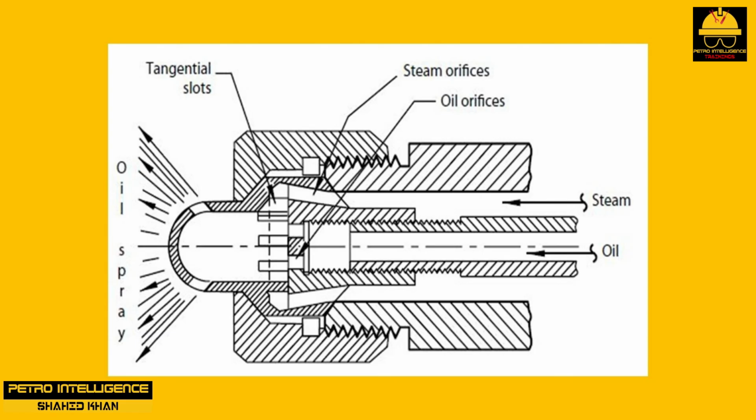The fuel oil flows from a circulating hot oil system kept at several hundred degrees F, depending on what is being burned. In most refineries, vis breaker or vacuum tower bottoms provide the fuel oil, which is circulated at about 500 degrees Fahrenheit. Burner tip plugging of the oil orifices shown in the picture is a routine problem. The most serious problem is loss of fuel oil circulation in case of an electrical power failure. The fuel oil can then solidify in the circulating system and in the burners themselves. For example, vacuum tower vis breaker bottoms can solidify at 300 degrees Fahrenheit.